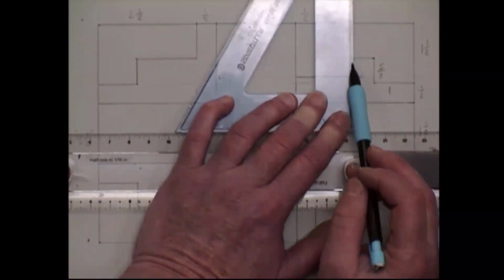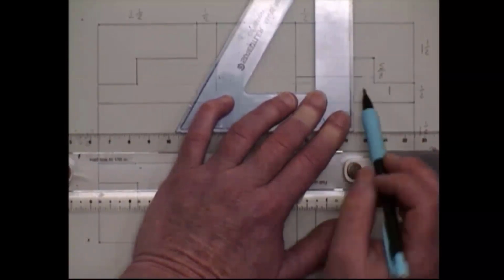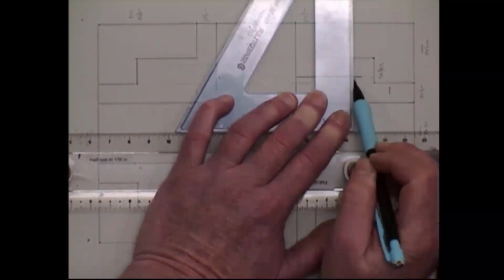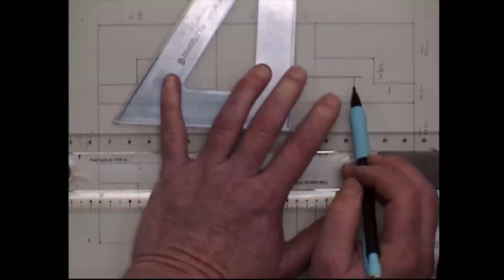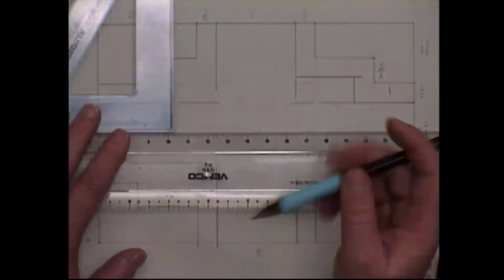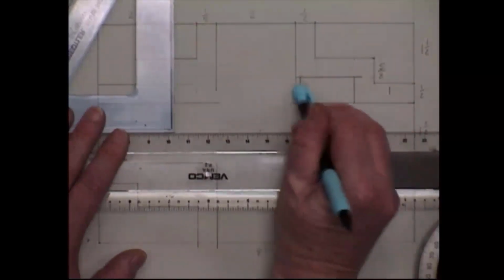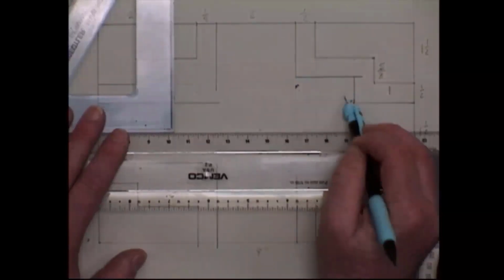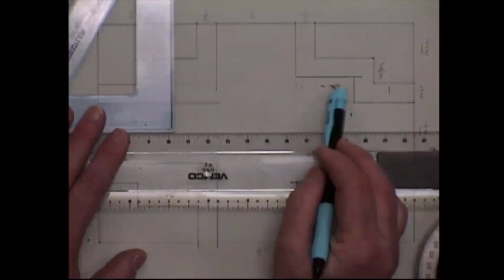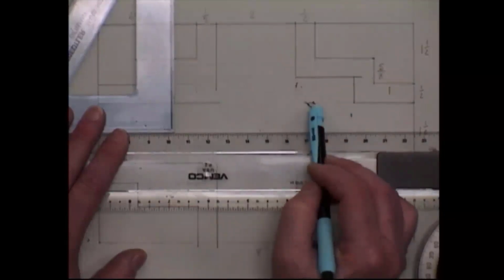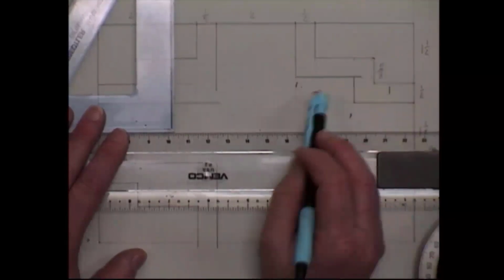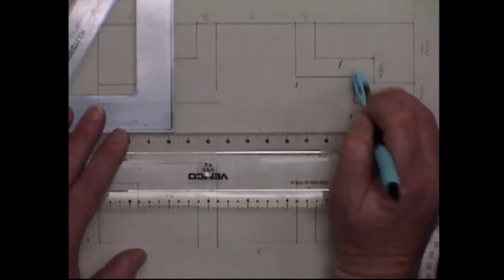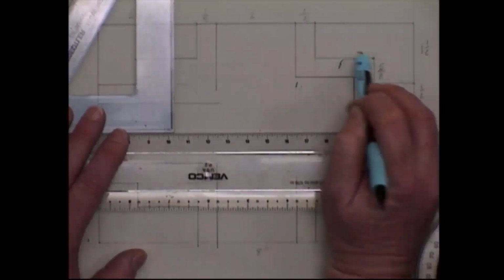So I'm lining my vertical straight edge up with that other 1/2 inch mark. And that line is actually only needed right here. So what happens here, we're going to end up erasing some of these lines that we made earlier. Okay, so now we have the corner part where we can erase it. And then we have this uniform 1/2 inch space all the way through. So we'll erase out in the space the lines that we don't need.